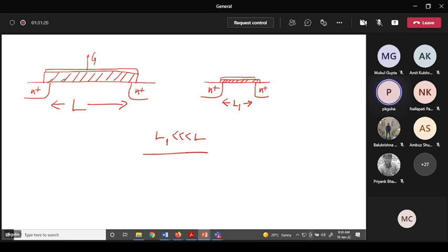If I don't do that, what will happen? The electric field between source and drain will be larger. So we need to increase the electric field from the gate side also, so that we can control the channel. Because in a MOSFET you form the channel by applying voltage at the gate. So here Tox needs to be reduced, right? Why does Tox need to be reduced? Because if we can't reduce Tox, we will not be able to control the channel from the gate side.